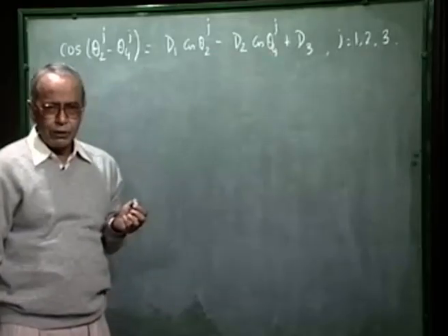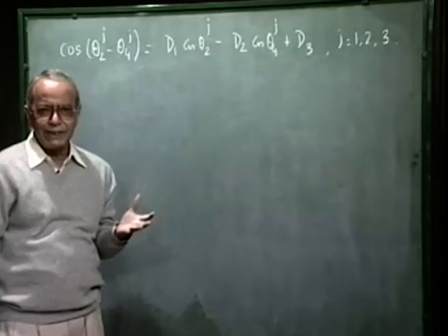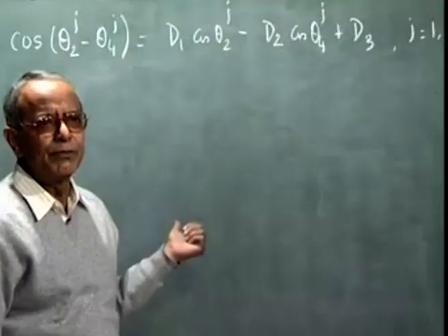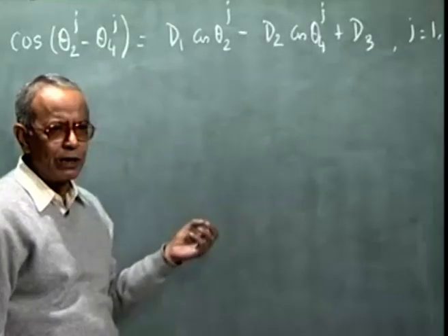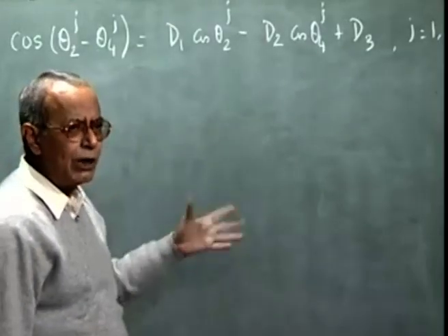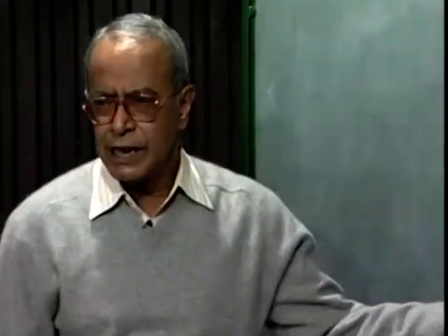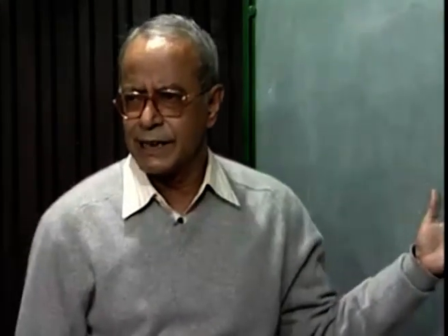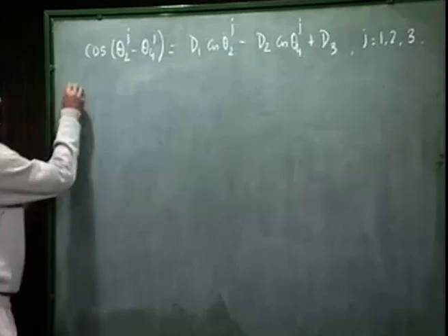It may be pointed out it is the link length ratios that matter, because if the whole figure is scaled up, we get the same relative movement between various links. That is, the linkage remains same, it is only the scale of the drawing. So, L1 I can choose arbitrarily or conveniently, and then we can get the other 3 link lengths L2, L3, and L4. This equation can also be used for generation of